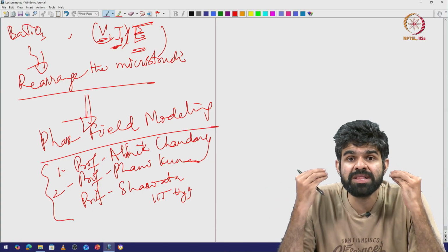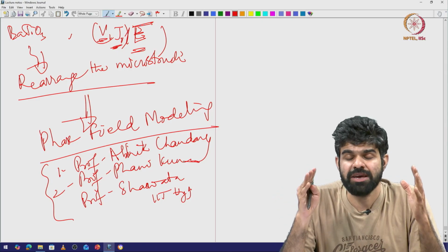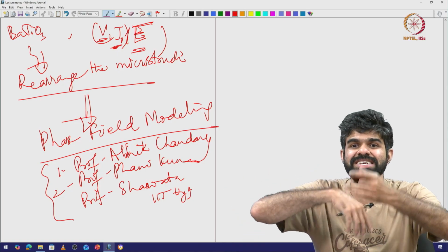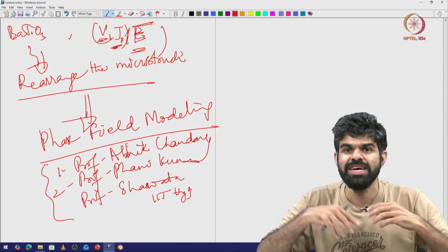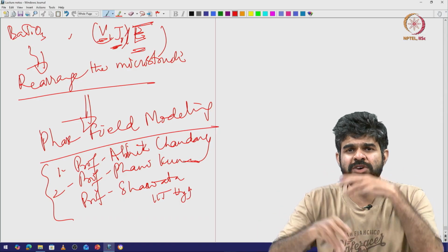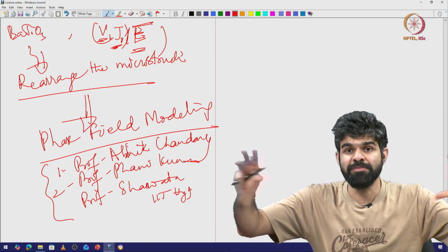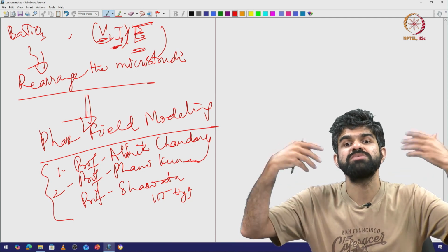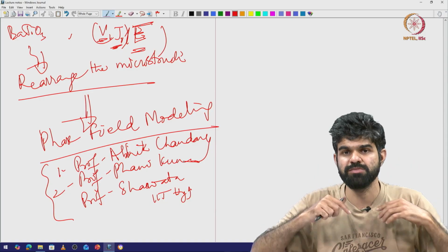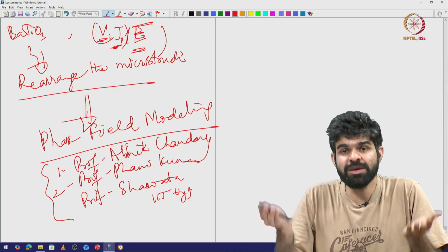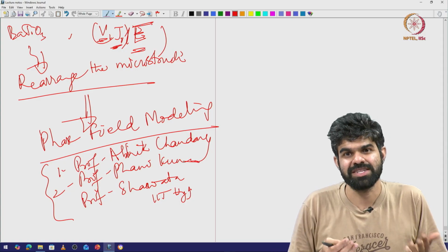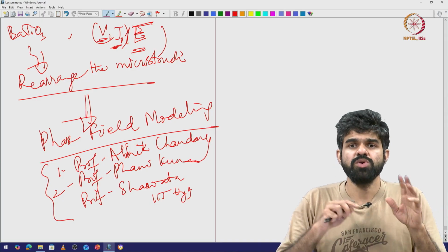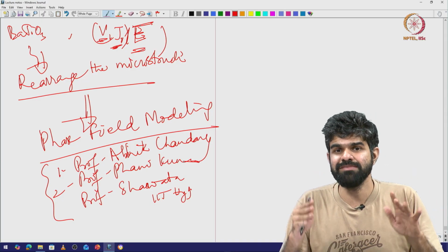The principle is simple thermodynamics. I fix G, I fix T, P, and then I let things reorganize themselves. I let all these internal constraints sort of reorganize themselves, just like the gases have interdiffused into each other, right. Let these domain boundaries form, they move. That is all completely non-equilibrium, but when it goes to an equilibrium, it goes to a certain microstructure, and this microstructure is what determines, so it is my final microstructure that determines the properties. Generally, it is not necessary that I have unique microstructures. That is why I have to do numerical simulations of these things, right. So, sometimes it gets stuck in some microstructure that is metastable, right.